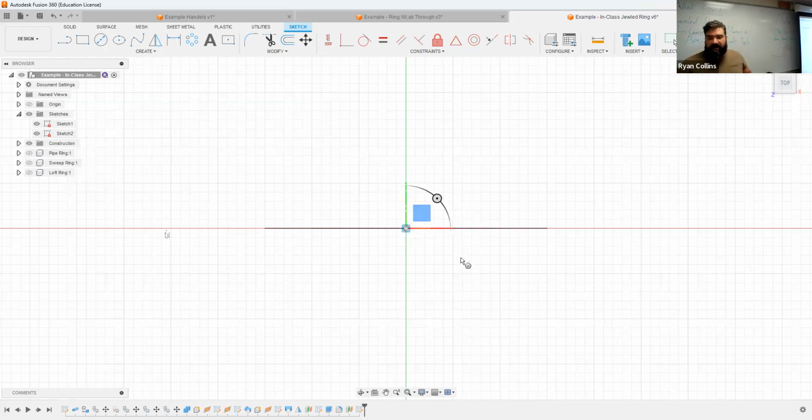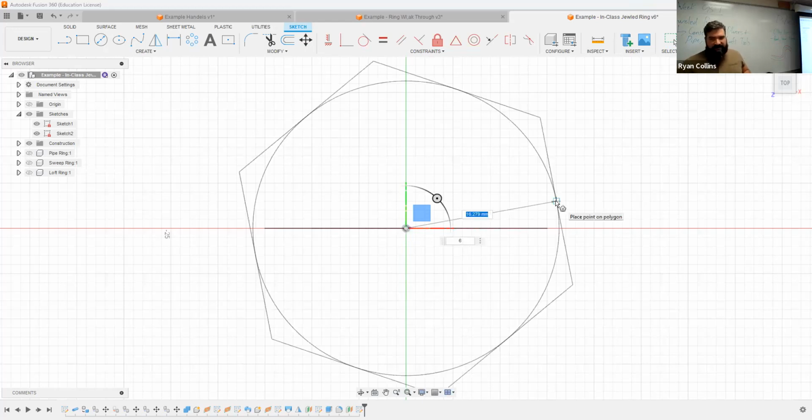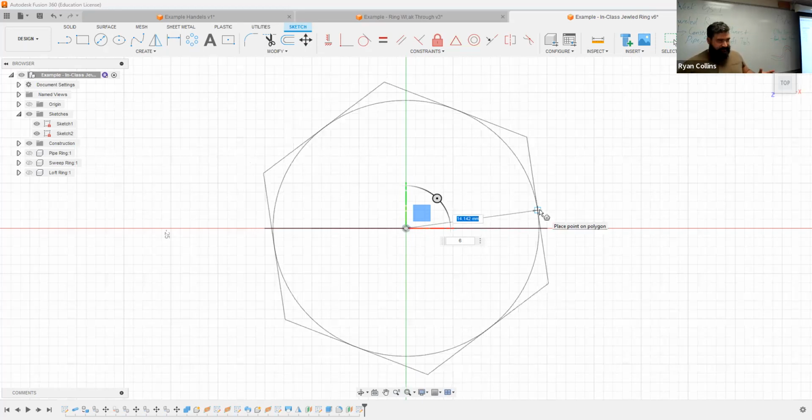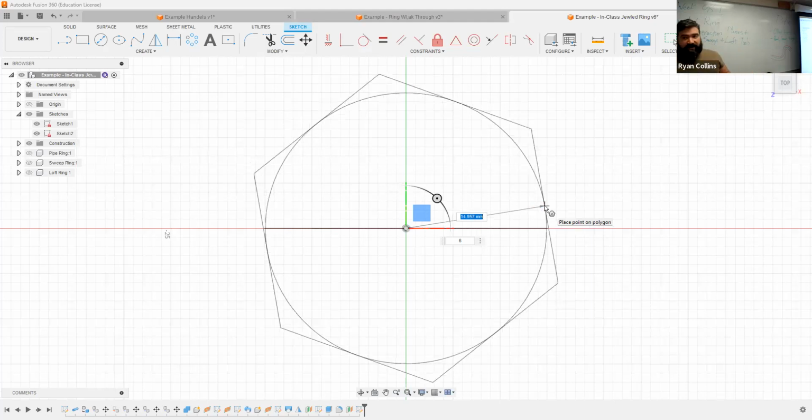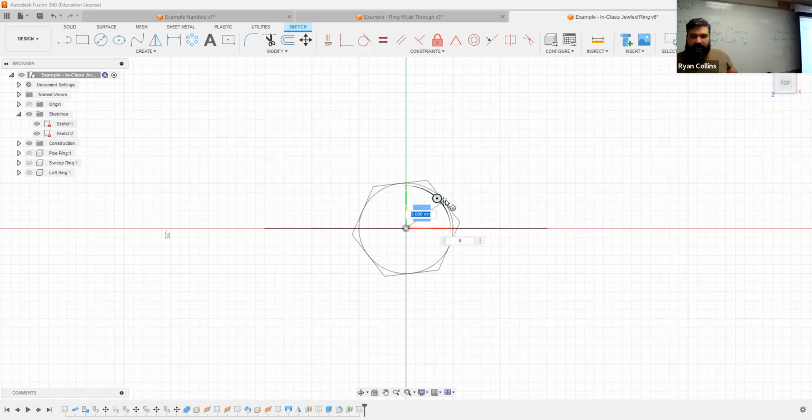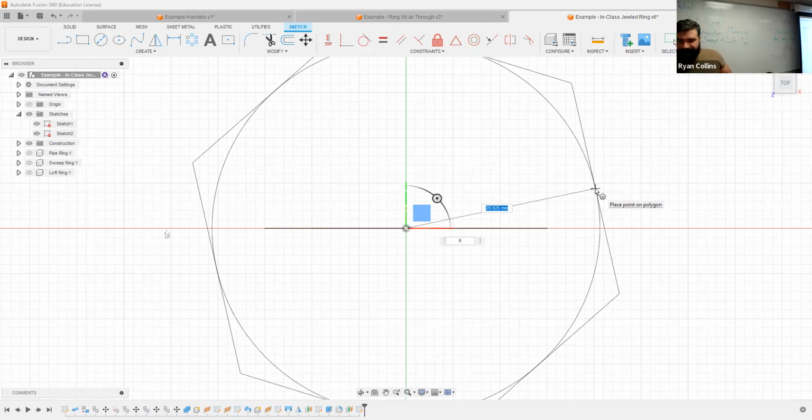Now, as I start, you can see as I draw outward, you have multiple options here. You have your dimension, how large that circle gets based off the radius. You have a floating toolbar here that says 6. So right now it's a 6-sided hexagon, 6-sided polygon, and you also have that rotation bar. Right now, the rotation and diameter are both being played with just by moving the mouse around. I am not clicking on anything.